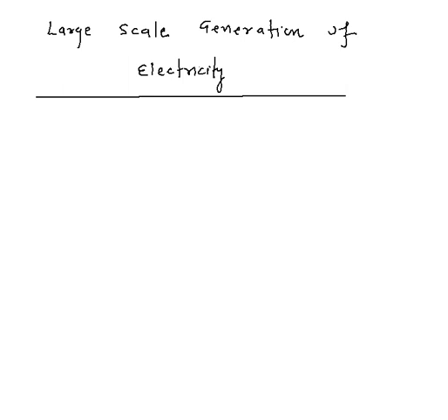So generally you use a coil along with something soft iron type of thing. You actually wind the coil around that soft iron core. The reason is that it helps in increasing the magnetic field because the core itself gets magnetized.